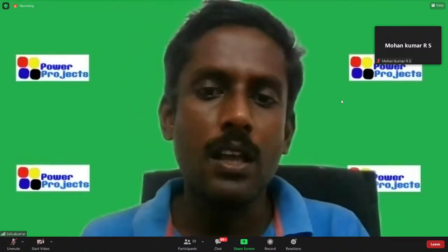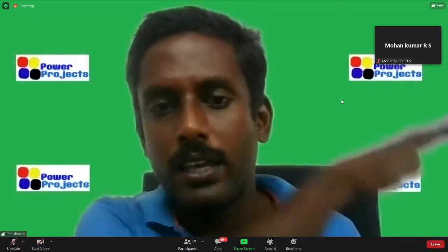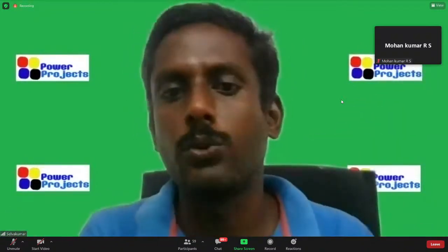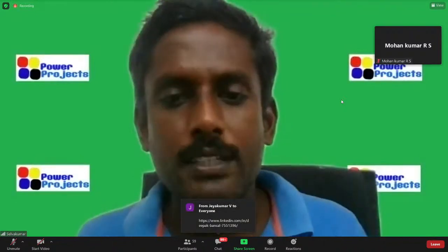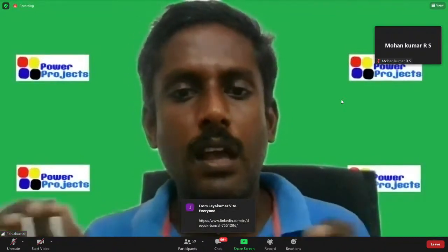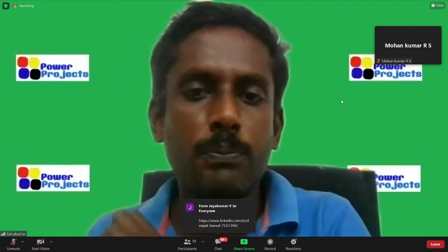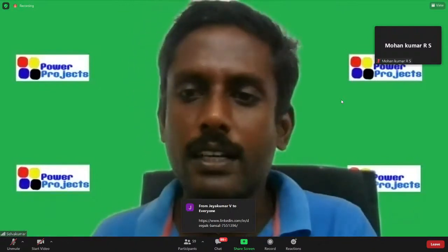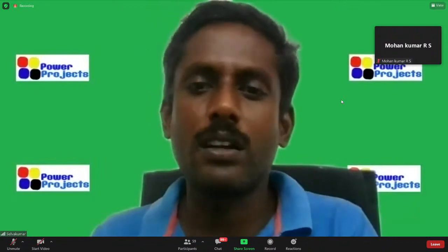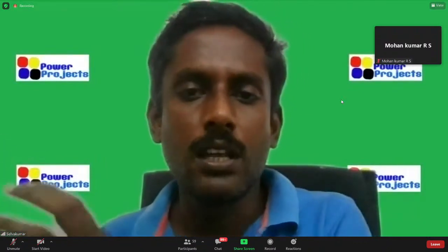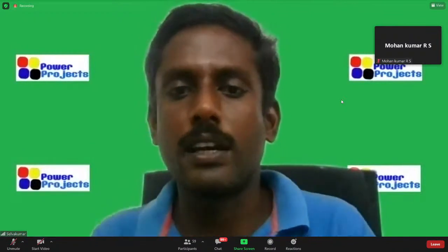You can go for a multi-layer soil resistivity, like 4 layers, which is available. For the time being, because of the time constraint, Deepak restricted it to 2 layers. You can go with multi-layer and optimize the earthing. On the other side, you can put non-uniform conductors wherever you want, or where there is a touch potential rise or a step potential rise, you can focus only on that particular area and reduce it.